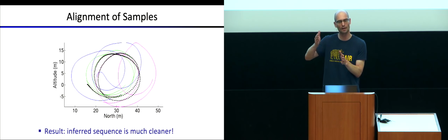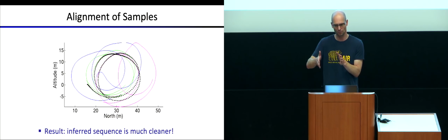So what do we do? We have a value function. Really what we get from running reinforcement learning in simulation is a value function that evaluates how good each situation is at any given time. And we use that value function to be able to look ahead only 2 seconds rather than needing to look ahead much further. That value function tells us how good it is to end up here. We also have reward at each time tick.